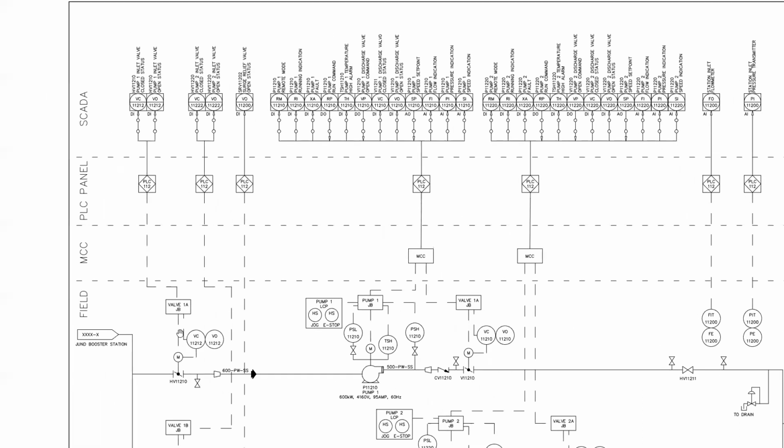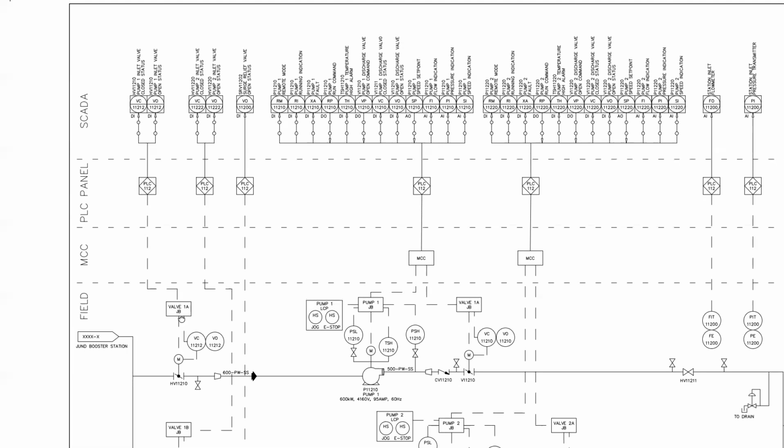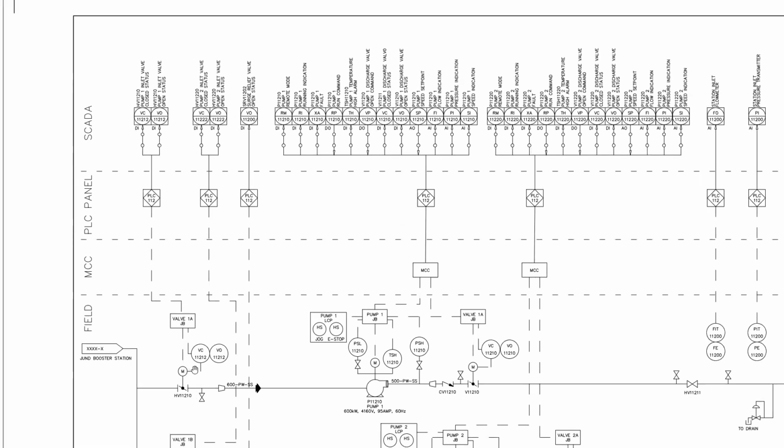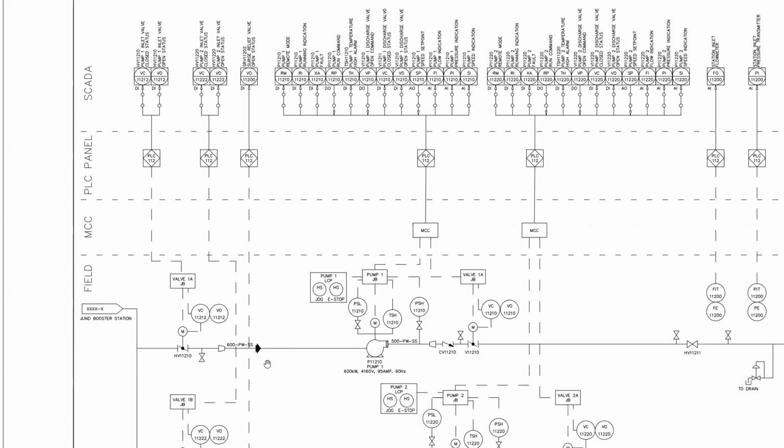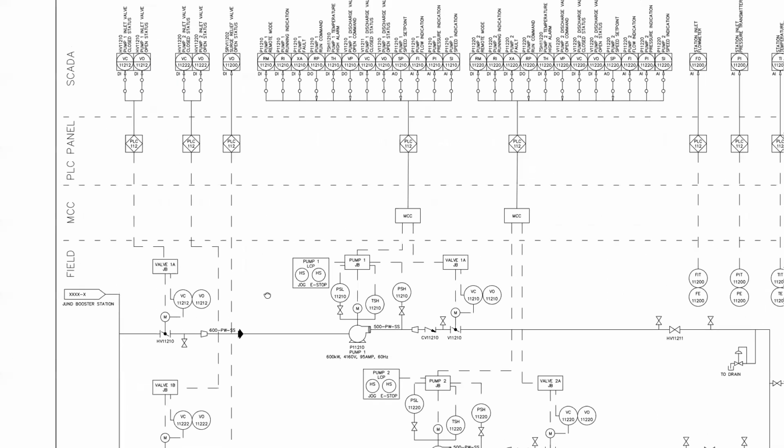So when we look back here at valve 1A junction box, there's an error there. Valve 1A and valve 1A should not be able to exist in two different spots in the same drawing. If they did exist in the same spot, they'd have to be shown that the wires came to the same spot. So there's an issue with that. If you caught that, good eye. Then you see here for this valve, we have an open and closed status. We have another open and closed status that comes down to the other valve.